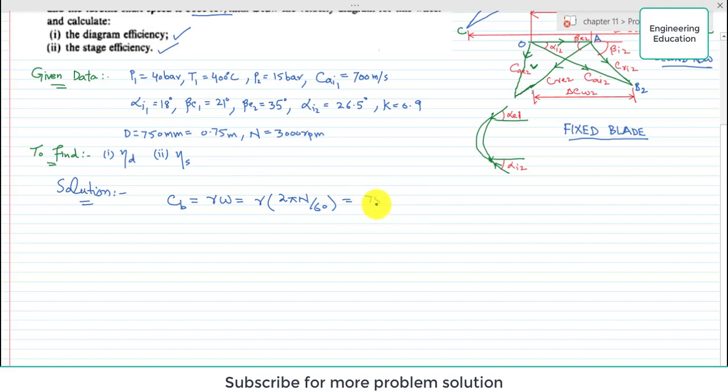We can write it like this: 0.75 by 2 into 2 pi into n, which is 3000 divided by 60. So these two will cancel. Simplifying this, we get the value of blade velocity, that is 117.8 meter per second.